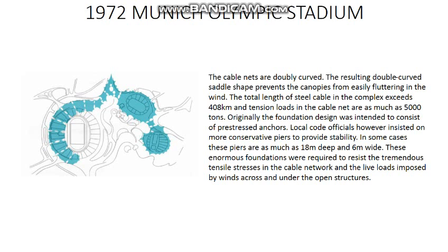Originally, the foundation design was intended to consist of pre-stressed anchors. Local code officials, however, insisted on more conservative piers to provide stability. In some cases, these piers are as much as 18 meters deep and 6 meters wide. These enormous foundations were required to resist the tremendous tensile stresses in the cable network and the live loads imposed by winds across and under the open structures.